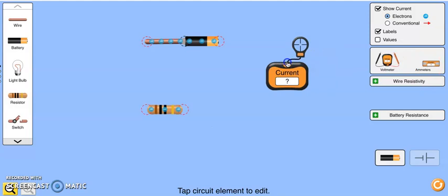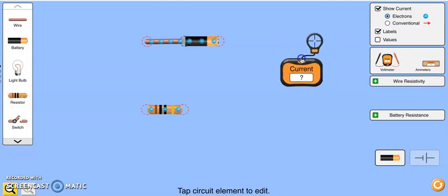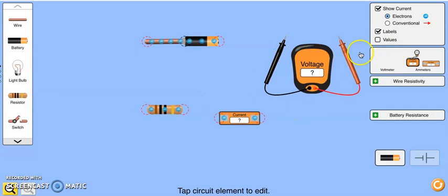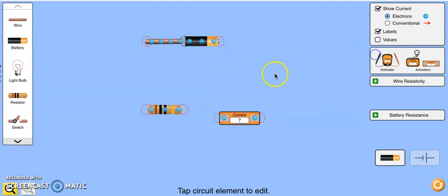This simulator has two. One is a cheat, which is not realistic for what we would have in a lab, so I'm going to avoid that. The other one is an actual one where you have to put it in the circuit. Okay, so an ammeter has to be connected in a circuit differently than a voltmeter. With a voltmeter, if I bring that out, I could just touch the two leads anywhere I wanted to and measure a difference. An ammeter, you can't do that. An ammeter has to be part of the circuit. It doesn't matter where you put it.